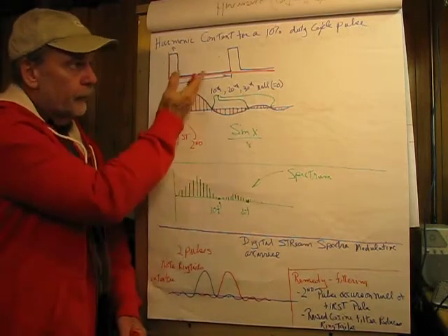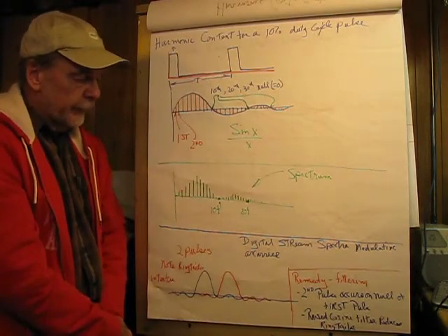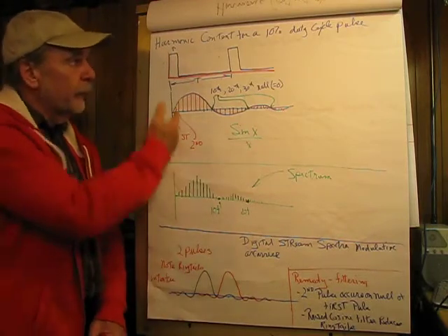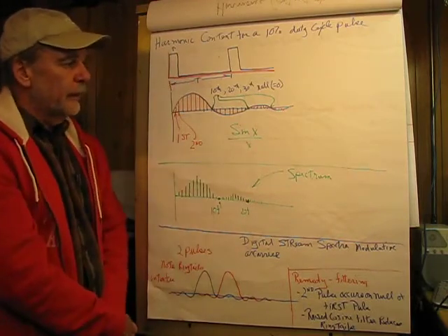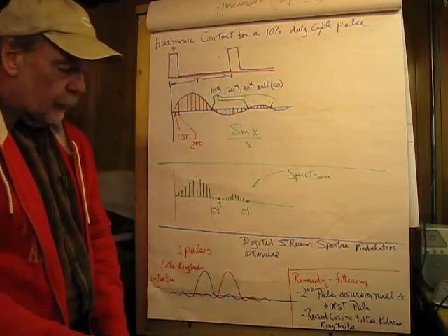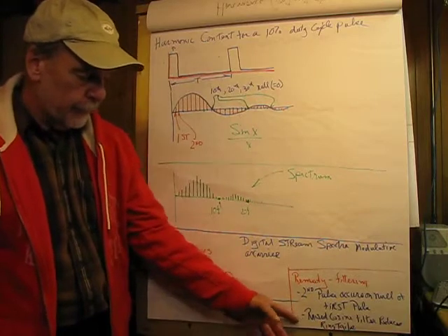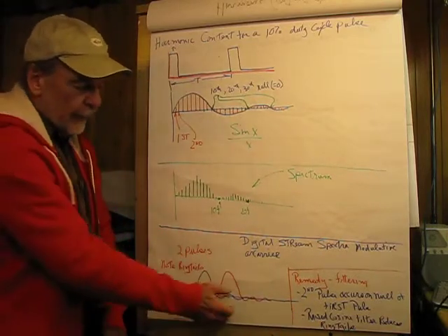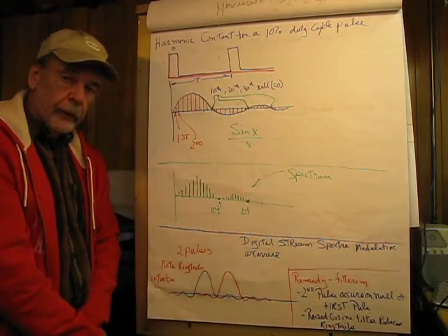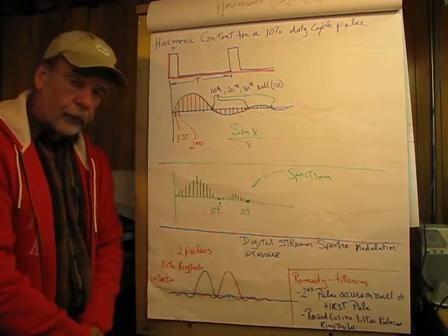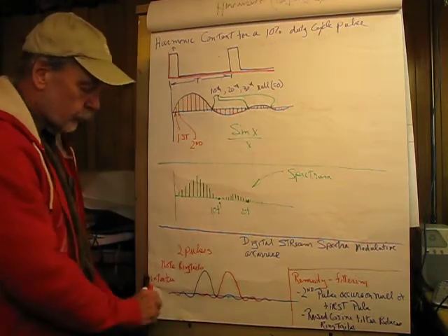Now, this isn't the best example to explain that, but that would be one of the things we want to do in the situation where we're dealing here with a 50% duty cycle waveform. The other thing we can do is there's a type of filtering called a raised cosine filter, and that has the ability to kind of squish the ringtails to attenuate them so they don't interfere with pulses adjacent to the pulse of interest.